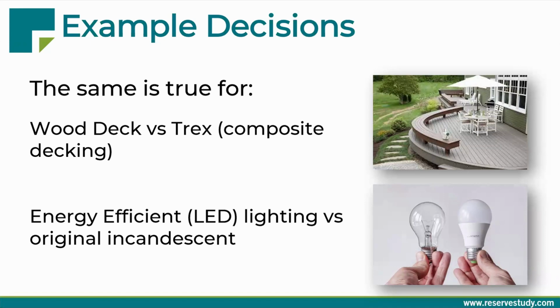Considering switching to LED fixtures, which are more expensive upfront, or conducting an LED retrofit where they can take your existing fixtures and remove the ballast from the fluorescent light, keep most of the fixture as is, and switch them to LED. This will have a huge cost savings benefit to the overall budget, your monthly utility bills, which will give you more flexibility across the board, including reserve funding.